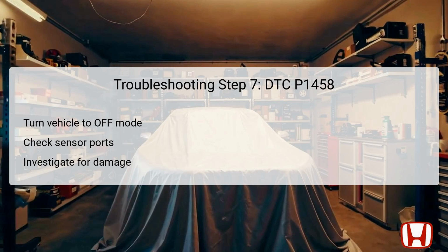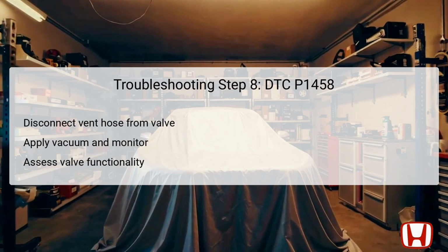Performing this visual check is crucial, as sometimes issues are not detectable solely through electronic diagnostics. Physical examinations can reveal unseen structural faults affecting the function. The final step involves a thorough check of the evap canister vent shut valve to determine its operational status.